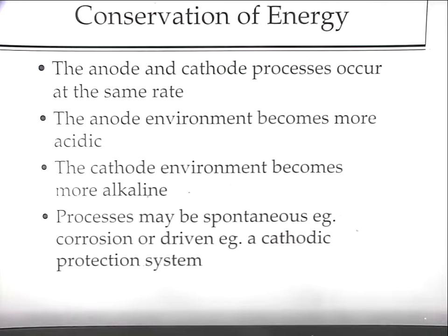And then lastly, there's just a note to remind you that the corrosion processes are spontaneous because the entropy is increasing, but you can put energy into the system and drive the process in the reverse direction, which is what you do with cathodic protection systems.